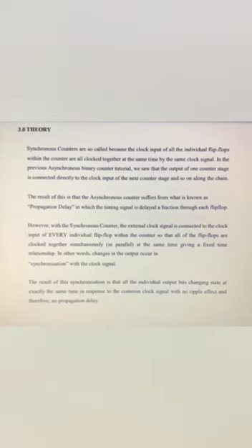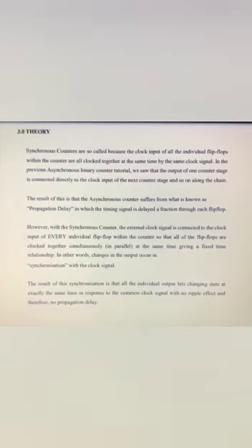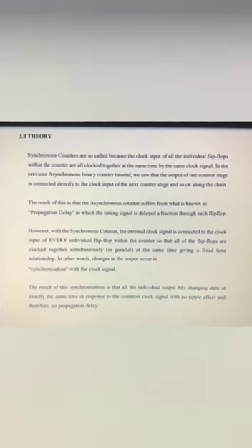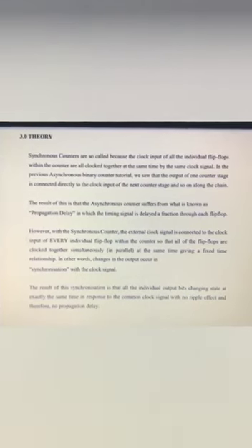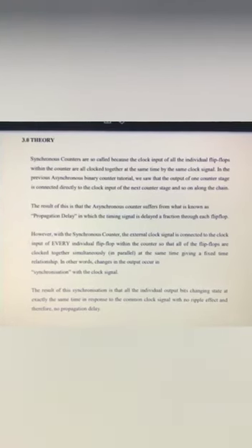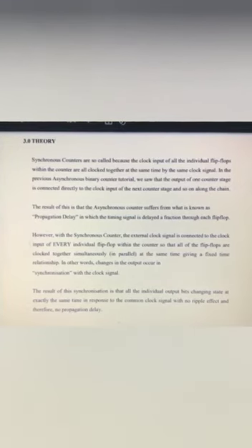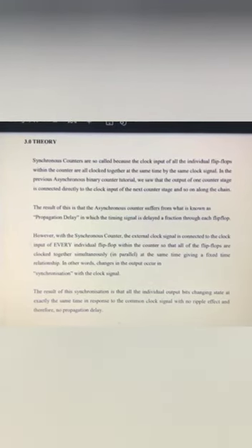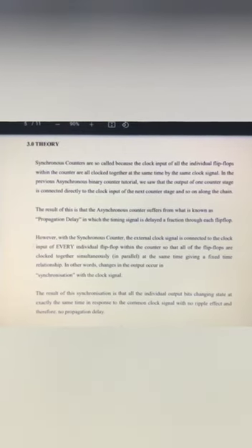A synchronous counter is so called because the clock inputs of all the individual flip-flops within the counter are all clocked together at the same time by the same clock signal. In the previous asynchronous binary counter tutorial, we saw that the output of one counter stage is connected directly to the clock input of the next counter stage and so on along the chain. The result of this is that asynchronous counters suffer from what is known as propagation delay, in which the timing signal is delayed a fraction through each flip-flop.